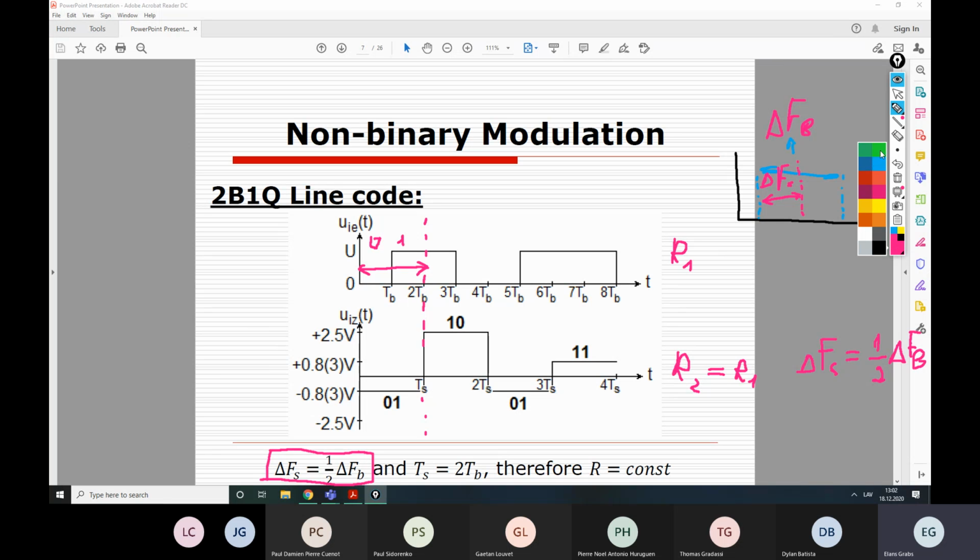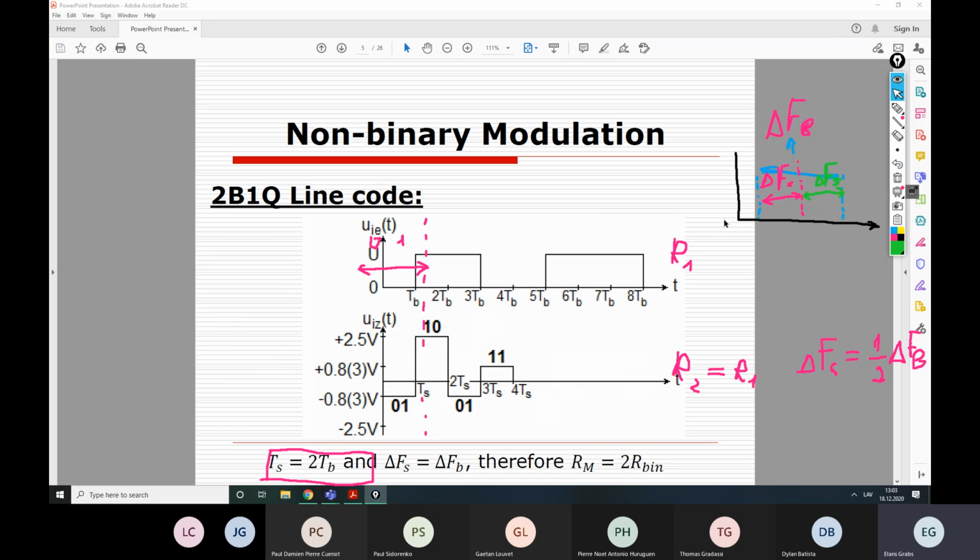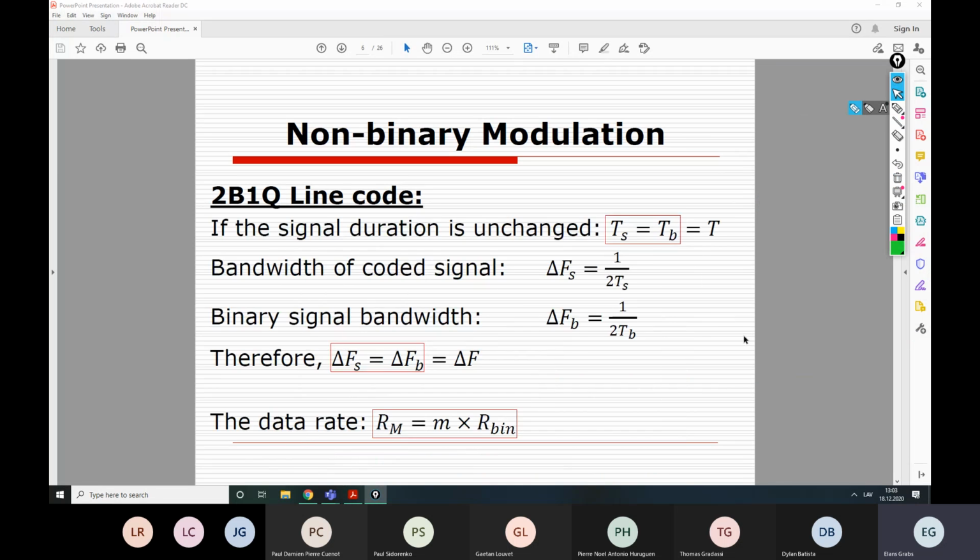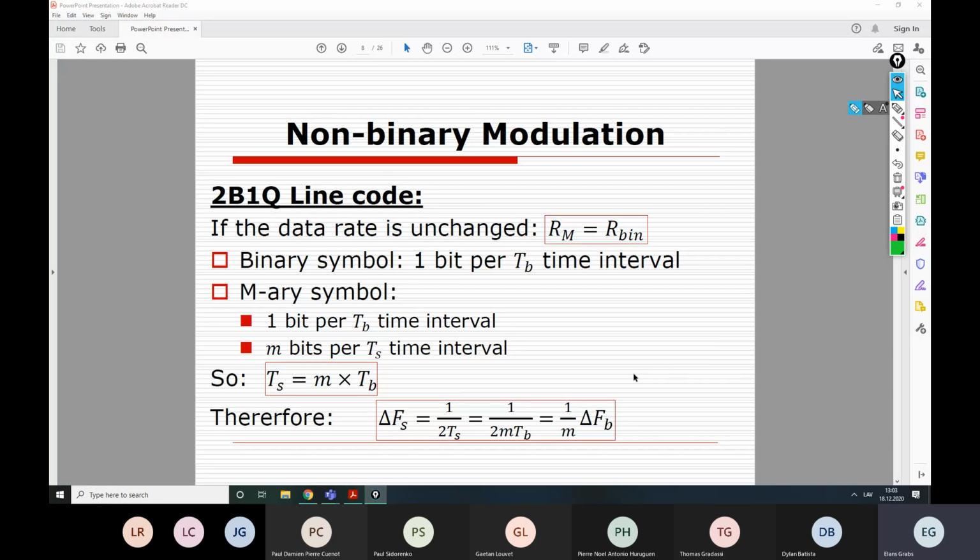And therefore we can actually use the remaining part of the bandwidth for the second signal with the same bandwidth. Now, instead of sending 1 signal with data rate R, we send 2 signals with data rate R. So basically, the total capacity of the system is still double, right? Only in this example, we divide this capacity between two users, but in the first case, we gave all the capacity to a single user. So either way, we increase the data rate of the total system.